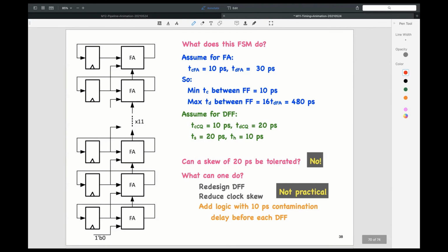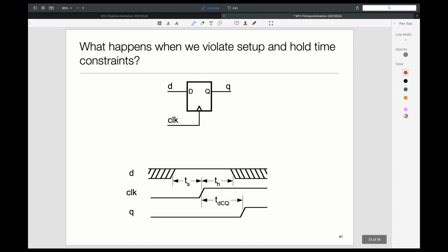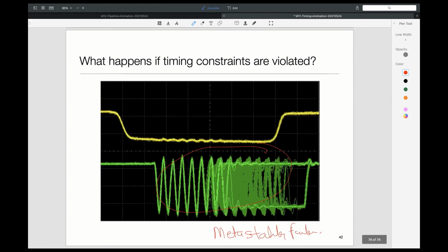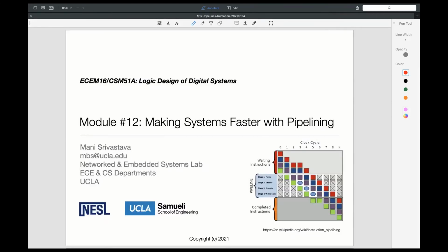So your best hope is to limit such violations at the boundary of your circuit. People create special flip-flops designed to have very good setup and hold time characteristics, and try to catch things there so that the main part of your system is not affected. I just want to mention that. It's a topic way too advanced for me to even attempt; I don't do that kind of work, so I can't say anything terribly meaningful, but those of you who take some advanced courses will probably encounter it. Okay, so let's see.